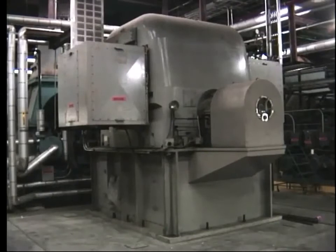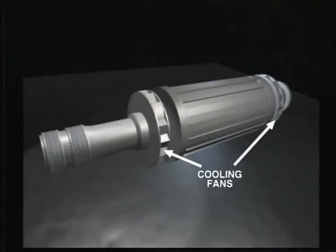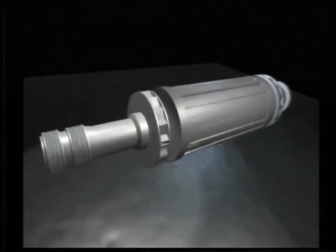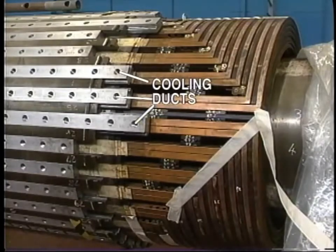For small turbine generator installations, air cooling is employed, usually open cycle. The air is actually circulated through the generator by fans, which are fitted at each end of the rotor. As the rotor spins, the fans provide the force to circulate the cooling air through the rotor and stator core. Cooling ducts are often built into the rotor and stator core to allow passage of cooling air.